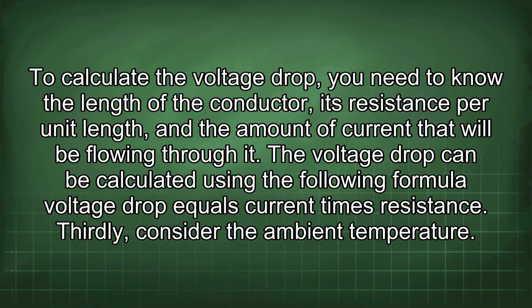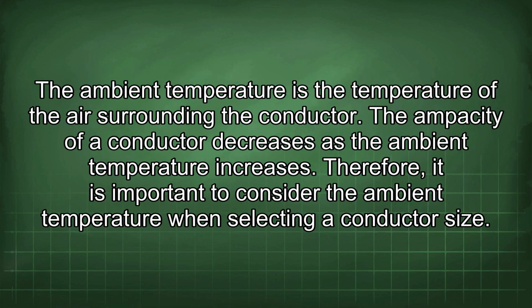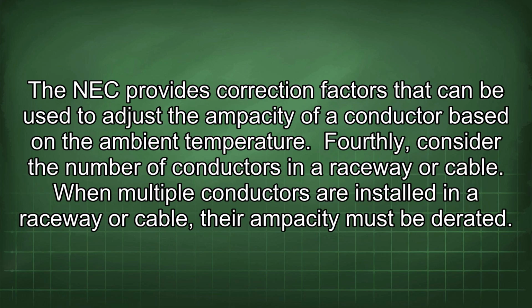Thirdly, consider the ambient temperature. The ambient temperature is the temperature of the air surrounding the conductor. The ampacity of a conductor decreases as the ambient temperature increases. Therefore, it is important to consider the ambient temperature when selecting a conductor size. The NEC provides correction factors that can be used to adjust the ampacity of a conductor based on the ambient temperature.